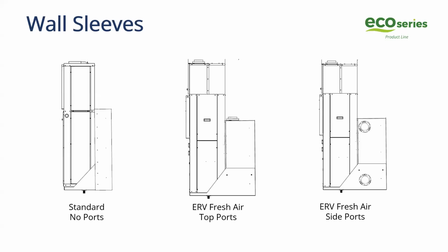I'll go into the ducting on that here in a minute, but basically by using these ports, you're drawing the air in through the louver on the unit, and so you don't have to have those additional dryer vent type penetrations to the building. So again, if you multiply it times 100 or 200 units with 2 penetrations each for a standard ERV, there's a lot of savings there, and it's just more aesthetically pleasing for the architects without having those penetrations.